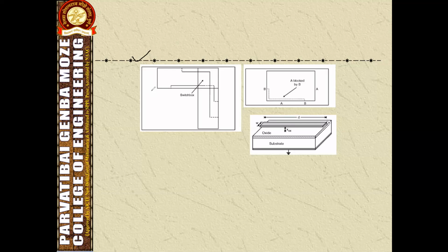The next figure shows the switchbox, mainly applicable to route the wire and track assignment at the end indicated by the point of the switchbox. This is the blocking example. In a switchbox, fixed pins are used to suggest layer assignment, and it applies the same layer to the route, in both horizontal and vertical assignments.